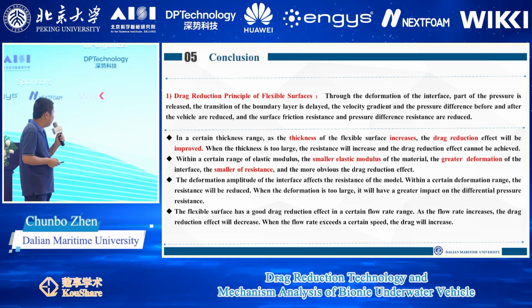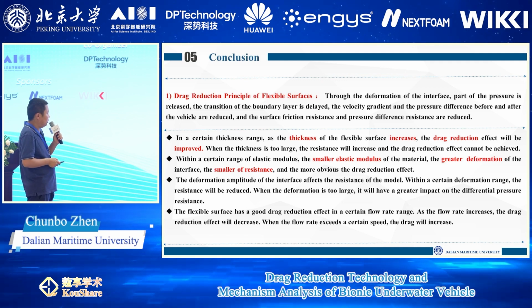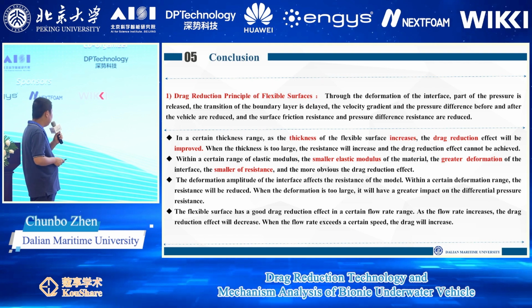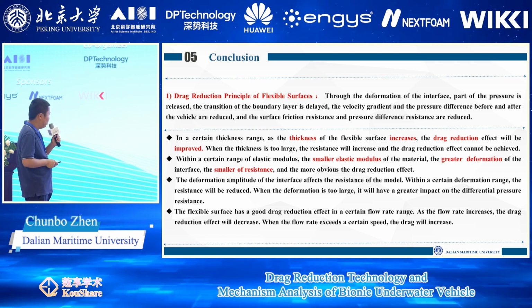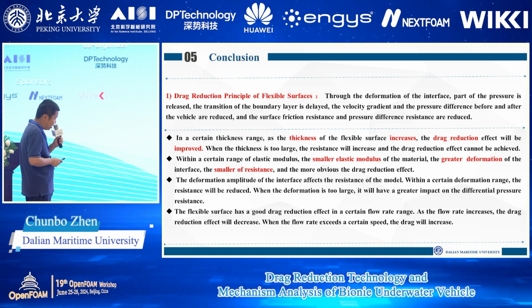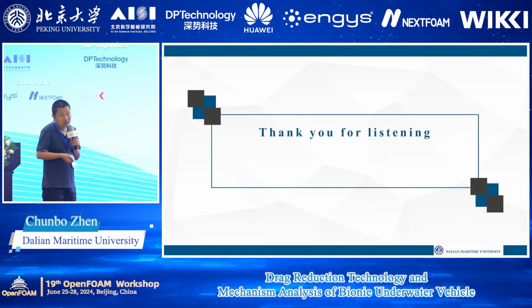The flexible surface has a good drag reduction effect in a certain flow rate range. As the flow rate increases, the drag reduction effect will decrease. When the flow rate exceeds a certain speed, the drag will increase. That's all. Thank you for listening.